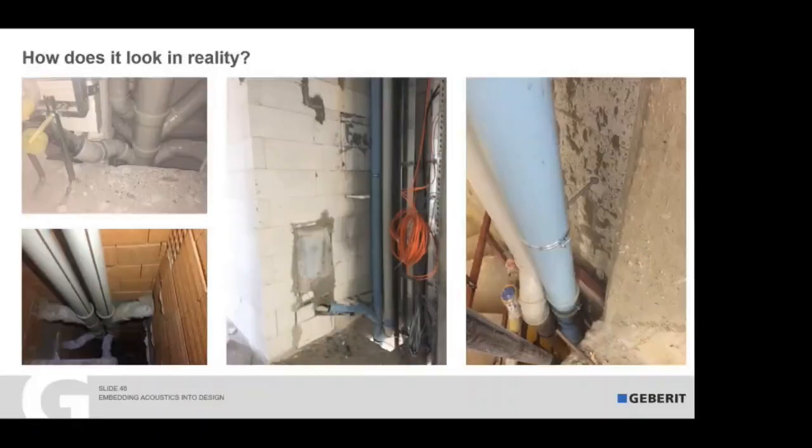So, acoustic data. Unfortunately, I showed already yesterday a picture, and this is also many times the reality. When you look at the build-ups here, you see completely installed pipes touching the walls. Then also here, a very complicated installation. Here, a Combi-Fix installation where the pipe is touching the walls directly. Also here, you see there's no rubber on the bracket. And there, of course, the most expensive piping system is not doing any help for the acoustics.